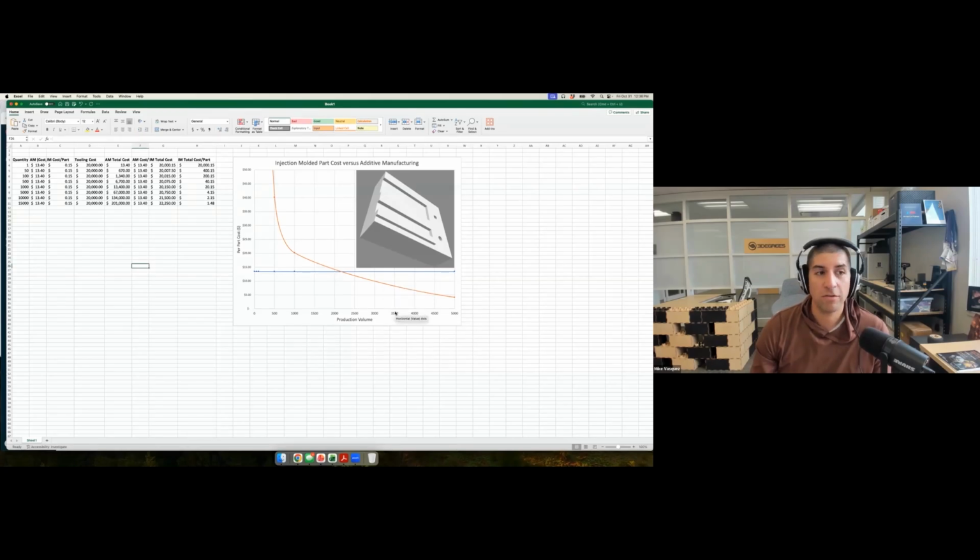So just to walk through my thinking, and there's more to go into on this, and I don't want to bore you with the gory details on a Halloween afternoon, but essentially when you think about 3D printing, yes, what I showed, there are cost breaks for parts, but once you get over 10 or 15, it's fairly flat. Because you're not making a tool every time, the price is the price. So whether you make 50 parts or 1,000 parts or 15,000 parts, generally the price stays about the same in terms of 3D printing.